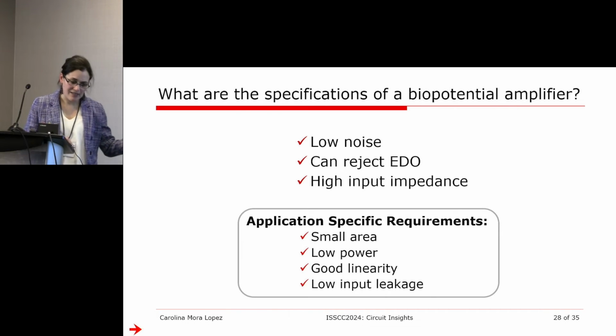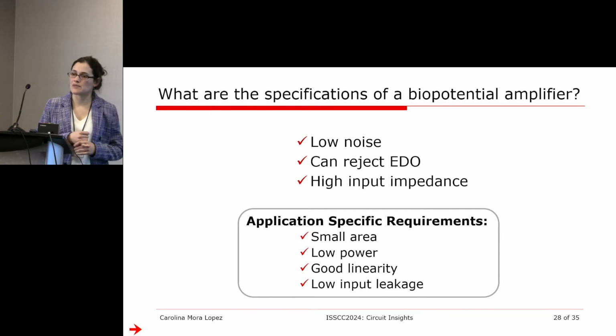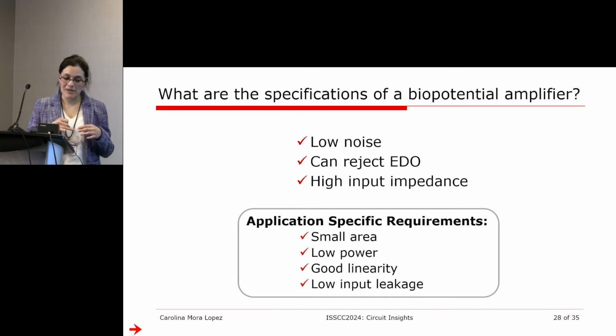Depending on the application, you may want also some requirements. You want your circuit to be small as well, especially if you plan to do a massive readout of many signals in parallel. You want to have low power. You may want also good linearity and low input leakage. But as mentioned before, there are many trade-offs here between all these requirements. So you will, as a designer, have to decide what is the best choice for the specific application.